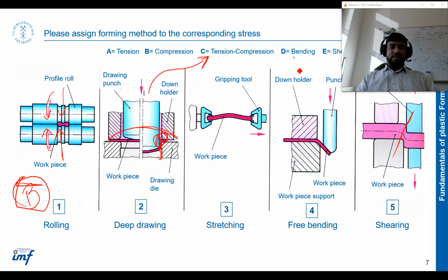Bending is the kind of procedure where we have a 2D kind of space where we are just applying a bending load and the sheet is bending in a certain direction with no tensile or compressive load. Here you will see that this punch is just bending this sheet in this direction, and the related force is not related to the applied tension. Interesting. That was quite an interesting case. It helps answer other questions as well.